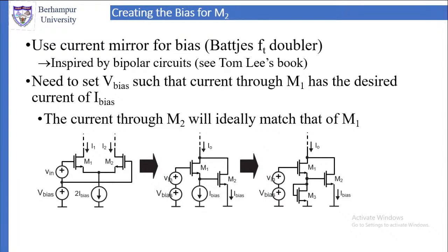Here what we have done is look at the first amplifier. Left side is the first amplifier, which is the difference amplifier. In the difference amplifier, the current that we see is 2 I bias. Corresponding to V bias, the current is 2 times I bias, that we divide in the second amplifier. Its equivalent, as we discussed in the previous case, the current is divided between the two devices M1 and M2. In each it will be I bias.